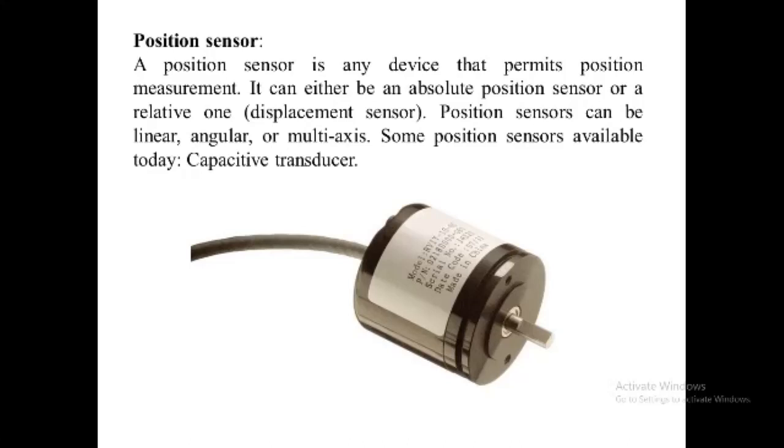The polarity of the output signal depends upon the direction and displacement of a moving core. The greater the movement of the soft iron core from its central null position, the greater will be the resulting output signal. The resultant is the differential voltage output, which varies linearly with the core position, and therefore the output signal has both an amplitude that is a linear function of the core displacement and a polarity that indicates the